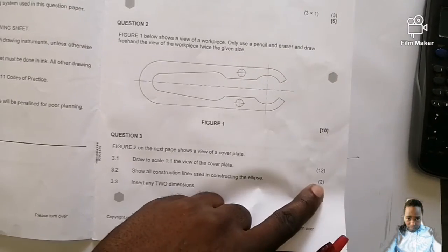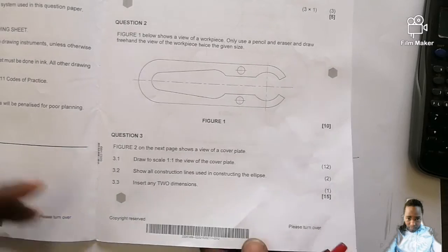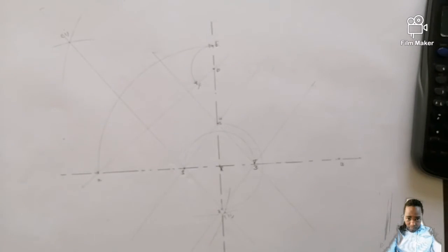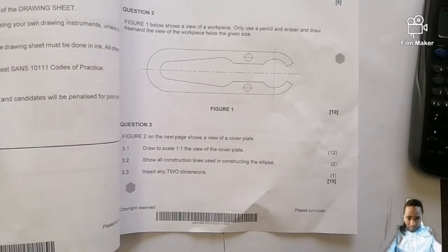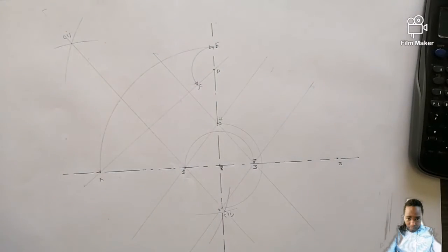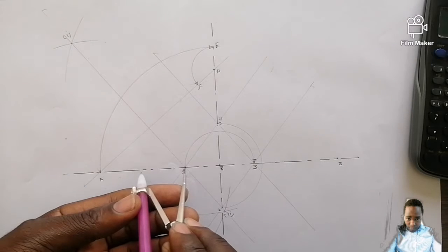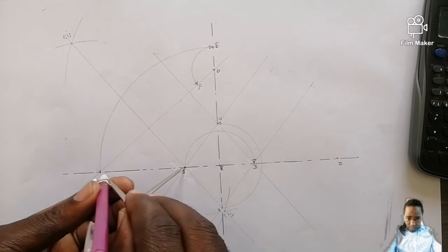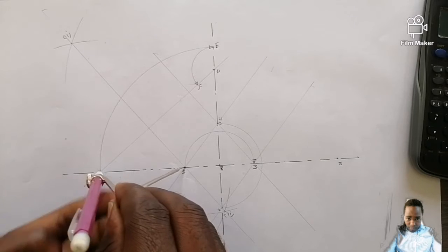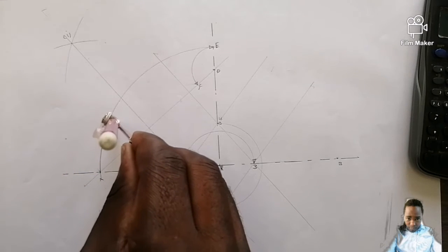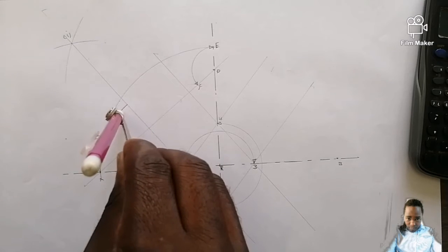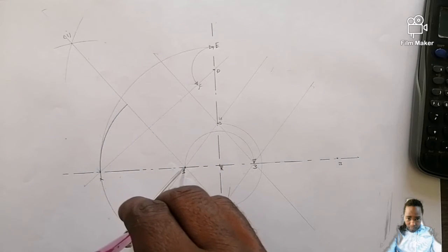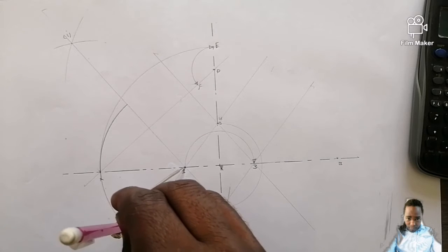So you'll be given 2 marks. Let's say in the examination they say time up. When drawn like this already, your 2 out of 15 is already yours. You understand? So now take your drawing compass. Let's construct our ellipse now. Place your compass in point 1. Further extend it to point A. Now draw dark. Once it touches the line of Roman figure 1 and Roman figure 2, you stop. Once it touches the line of point 4 and point 1, this side, you stop.